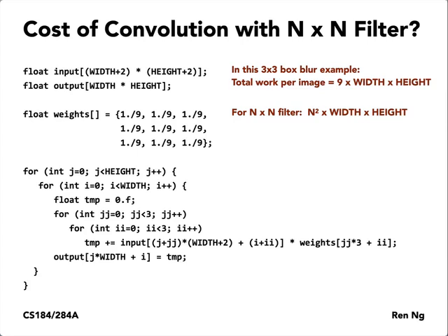And remember, in a digital still camera, it's a hard spec because you click the picture, and then what's the first thing the person wants to do after that? They want to hit the play button to look at the picture they just took, right? So if you want to apply all your image processing immediately after the picture's taken, you have to run this kernel. And if it's a 13 by 13 denoising filter, you need to run all of those operations over, say, a 10 megapixel or larger image, in a very short amount of time.